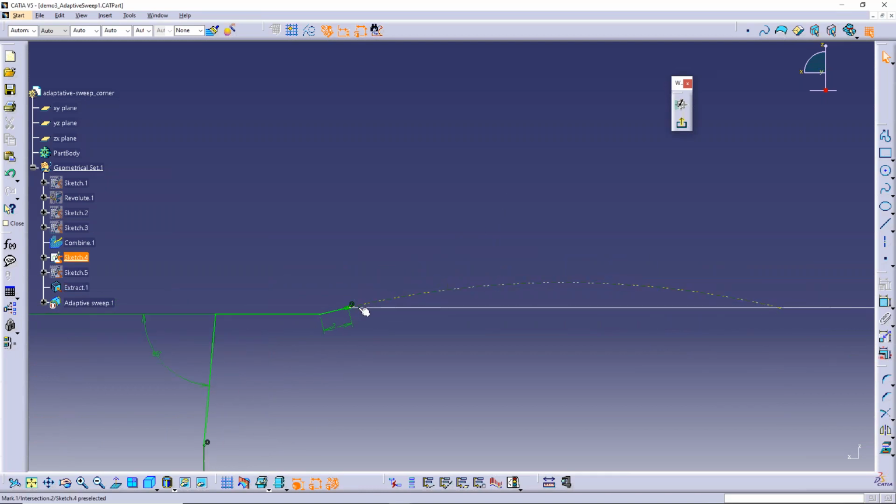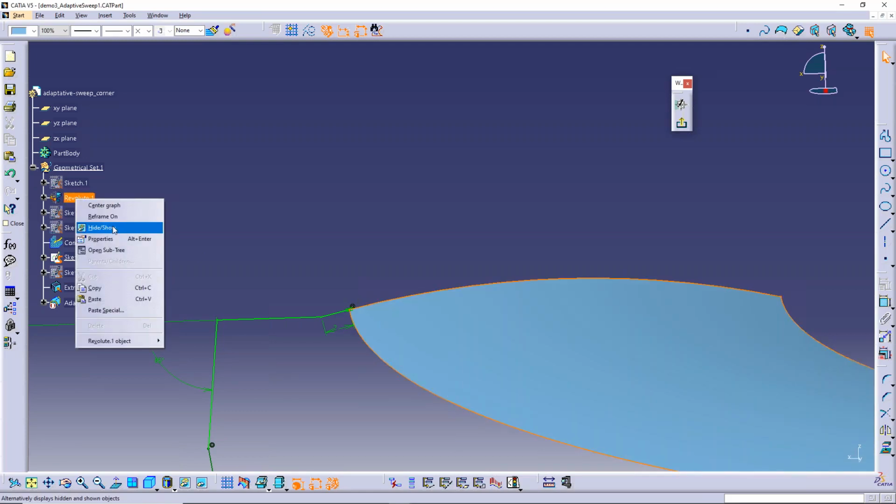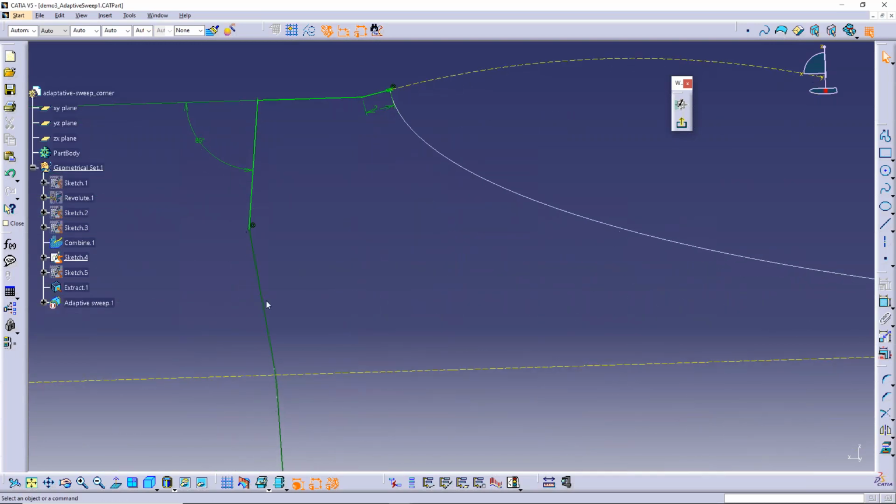But let's look in here, right? There's a coincident constraint here relative to another curve. This curve right here is actually an extracted boundary from a surface that I hid, as a matter of fact, this revolute here that you see now. I'll go back and hide it because it's visually distracting, but that boundary curve right there was extracted from one of the boundaries of another surface feature. And there's an actual connection there between this sketch and that surface and boundary. There's another coincident constraint down here at the bottom or end of the section to yet another curve. That's a combined curve element right there.